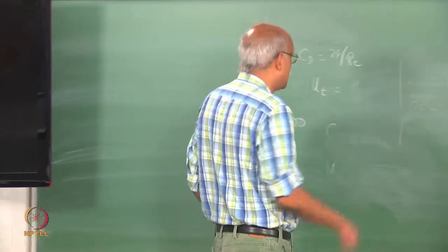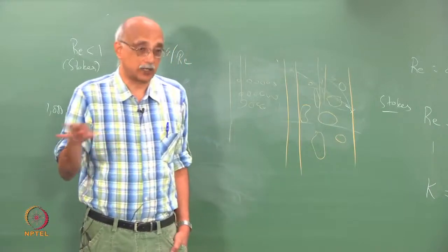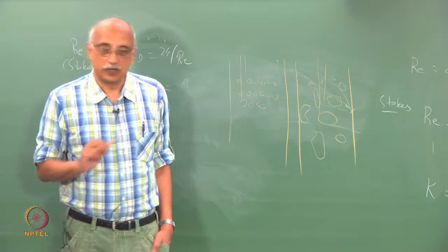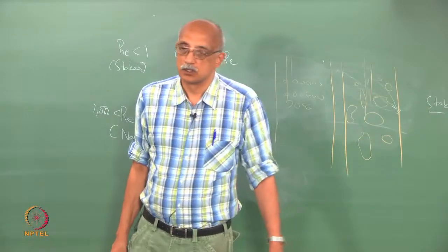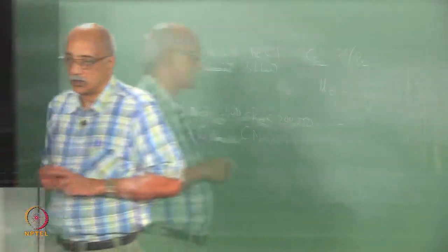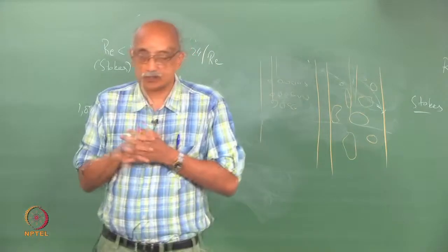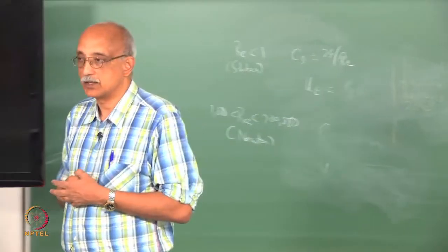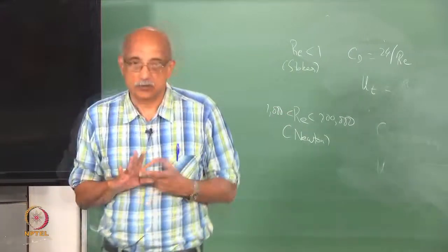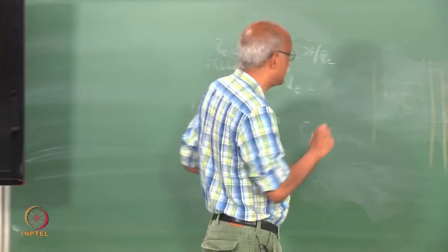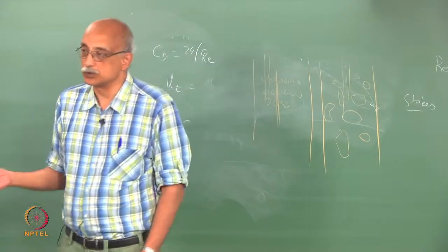So if you are flowing fluid through here versus through here, while you are still in the packed bed mode, you will find that the pressure drop will be greater here compared to here, because you are trying to force fluid through a bed that is more conforming and allows fewer passageways, whereas in a bed with all spherical particles, it's more possible to have many pathways for the fluid to move through.